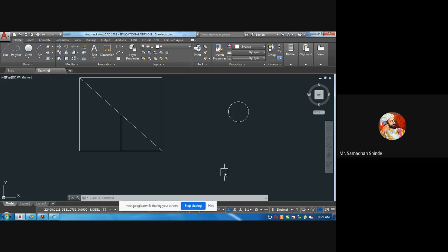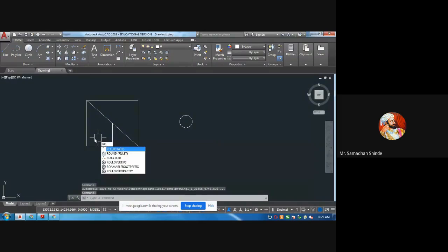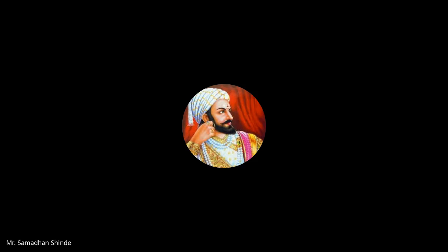Then what is the rotate command? You can select RO, enter. RO enter. Rotate, RO enter.